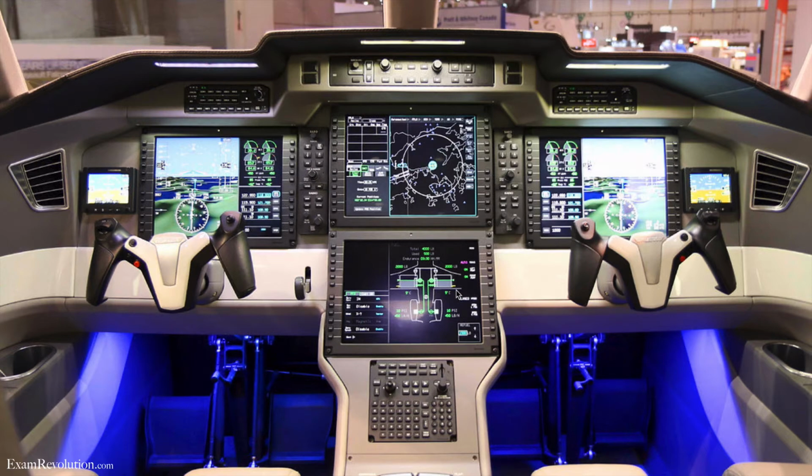It depends on how much space there is in the cockpit, and also the type of manufacturer that's making the avionics. Like for instance, the Pilatus has got the Honeywell avionics, right? And so you can see on the primary flight display over here, I don't know if you can see it properly, but you can roughly see there's your airspeed on that side, there's your altitude on that side, there's the vertical speed indicator. You've got a few of your instrument or your engine parameters over here. Then you've got your radio frequencies and your nav frequencies for like your VOR stations and so on. And then also on that same screen, you've actually got your HSI, okay, your horizontal situation indicator.